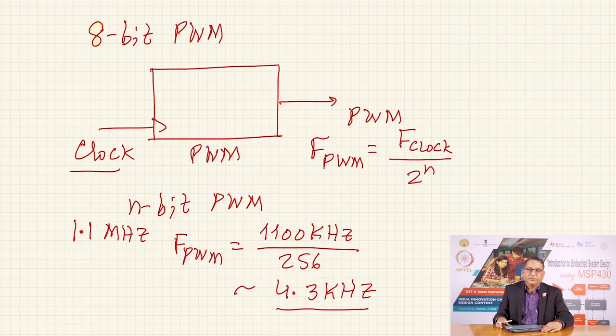Therefore, it is very important that we have a high frequency of the PWM signal, but the PWM frequency is largely determined by the system frequency, that is the frequency at which the timer is being clocked. As you know, I can dynamically change, or at reset decide to have, an arbitrary value of the clock frequency.